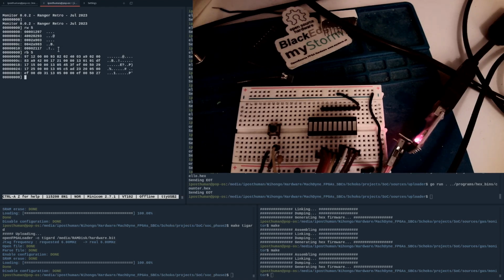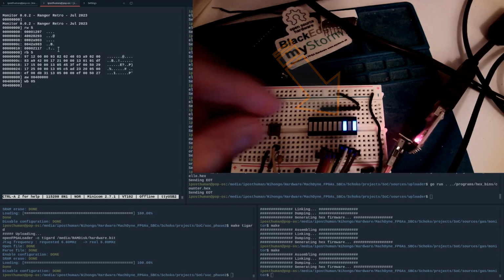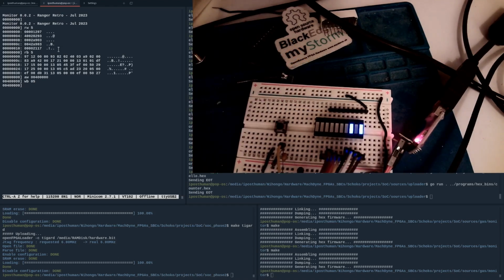We just need to set the working address, and Dave Ho's style was to actually set the working address. Over to the left of the cursor is the address. So if we go AW, we put in the address of the 2345 here. That's the address of port 5, and now we can write any kind of byte we want to it. So I'll write a 5. There's the 5. Excellent. And now I can write any other value like 42. And there's 42. I can write 55. There we go. Excellent.